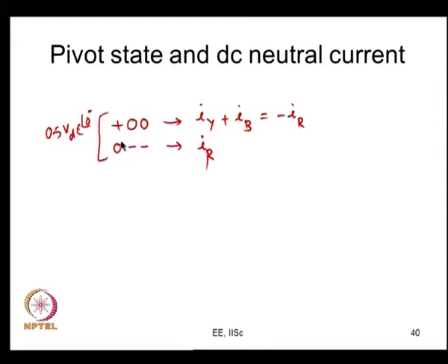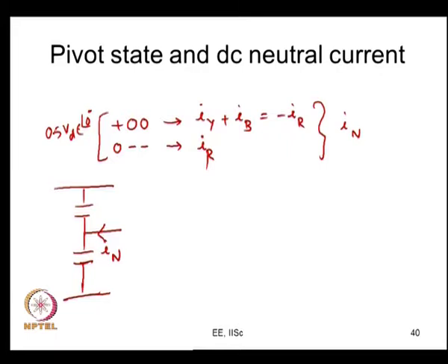This DC current flowing through that, what will it cause? If, for example, you have this DC bus, and through this midpoint some current flows, let us call this I neutral, IN. This is going to charge or discharge in some particular direction, and this is going to lead to voltage unbalance. That is, this voltage V1 and this voltage V2 may not be equal.